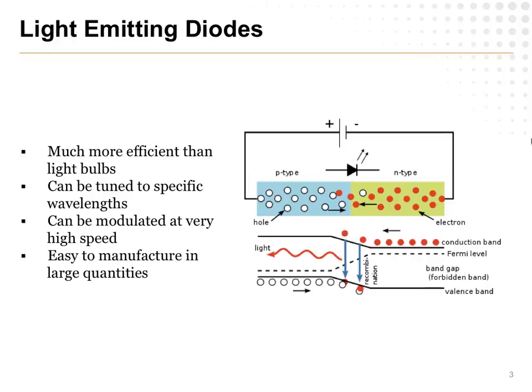And even under very ideal conditions, the best you can get is maybe, I don't know, 100 hertz tops, if I had to guess. Not a whole lot. You're limited to many milliseconds of rise time and fall time. LEDs, however, even a cheap, crappy one, can easily be microseconds of rise time and fall time. And I think you're kind of inherently limited by the internal capacitance of the LED for that sort of thing. But in principle, they can get very, very fast.